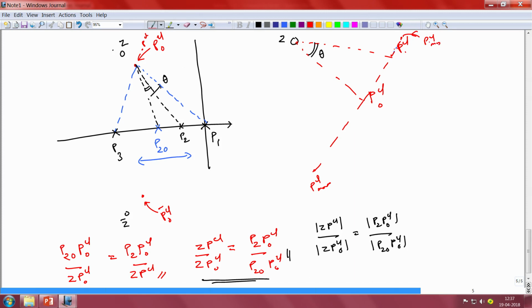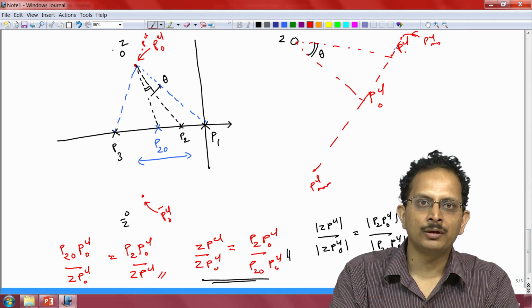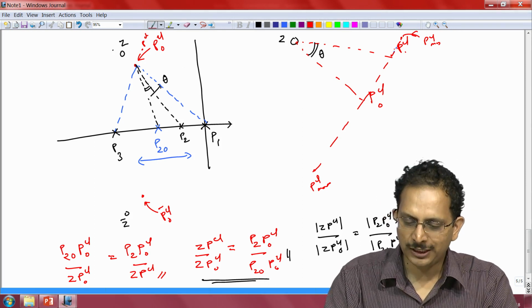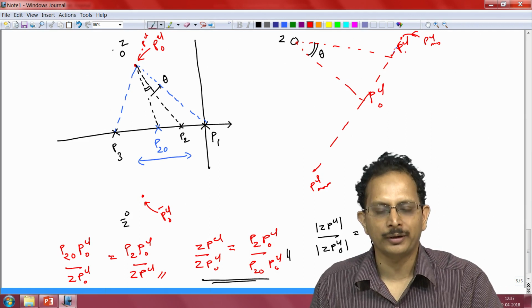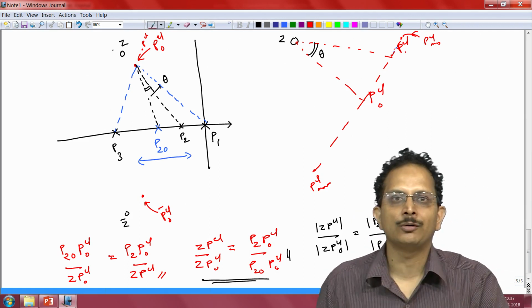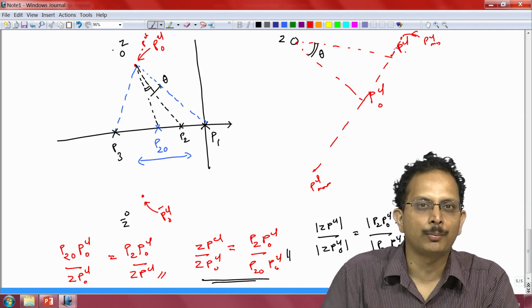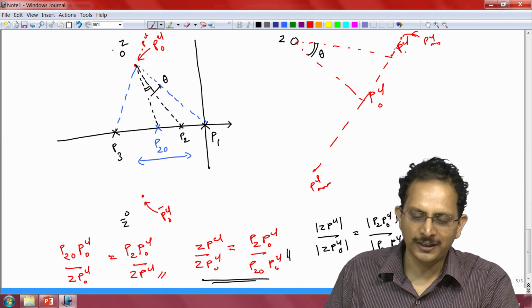So PCL min corresponds to the closed loop pole location when the plant pole is at S equals 0. PCL max represents the closed loop pole location when the plant pole is at S equals -2, or coincident with the point P3 in this schematic here.